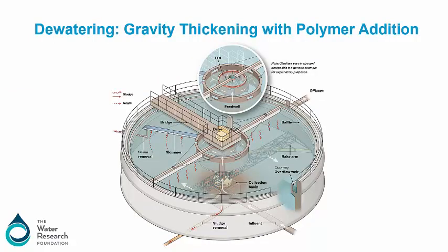Thickening is a dewatering process by which biosolids are condensed to produce a concentrated solids product and a relatively solids-free supernatant. Gravity thickening uses the natural tendency of higher density solids to settle out of liquid to concentrate the solids. Polymer is added to aid in the settling. Gravity thickening is required for certain phosphorus recovery technologies and nitrogen recovery technologies, including ammonia stripping and ion exchange.